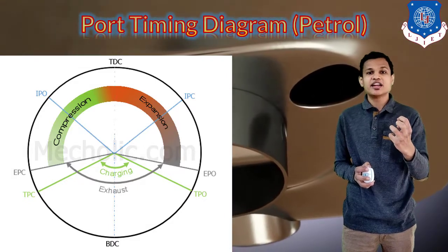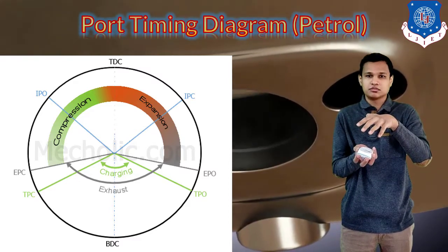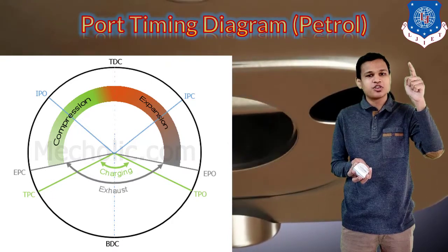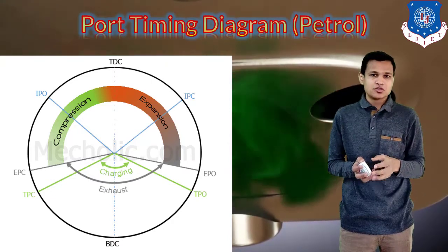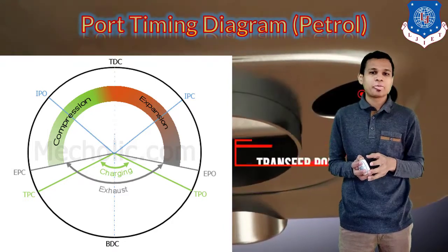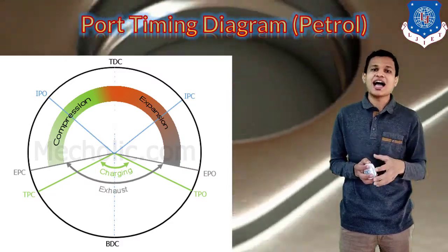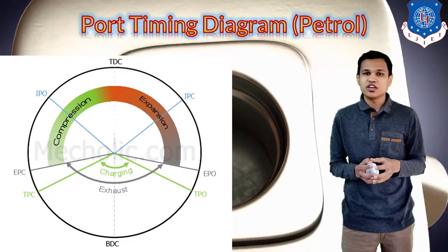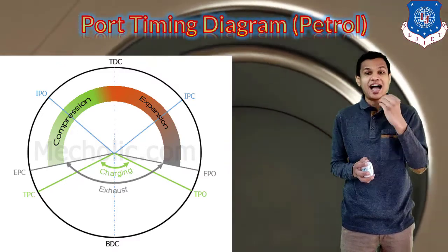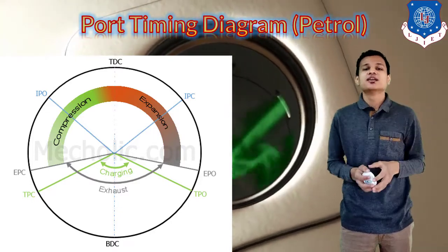After that, I have said earlier as well that the inlet charge will be compressed in the below part of the piston. After compressing the charge, we are transferring it from the transfer port towards the engine. When we are transferring the inlet charge via the transfer port, it is being compressed, so it has a higher pressure. Because of the higher pressure, the inlet charge will push out the exhaust charges, because of the higher pressure that it has attained from the compression below the piston.